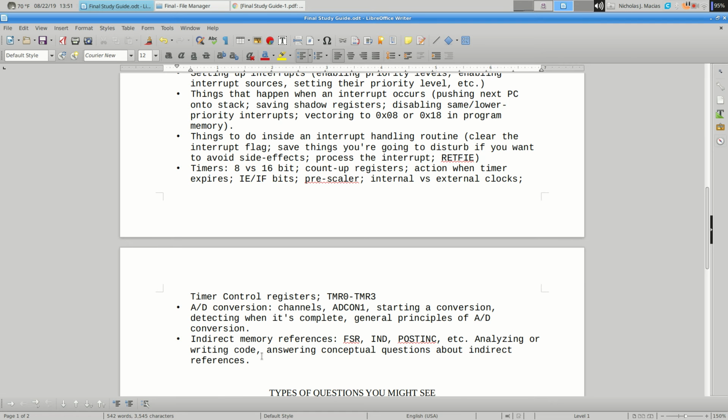So you take all of that and you can generate a certain delay until an interrupt happens by loading an initial value into timer 0, high and low. The closer you start it to the overflow point, the sooner it's going to overflow. If you start those timer registers at 0, it's going to take a long time till it overflows. If you start them really close to the largest value that they can store, it's going to overflow very quickly. So you can adjust your timing till an interrupt happens by tweaking those parameters. How many bits, what the prescaler is, and what the initial value is.